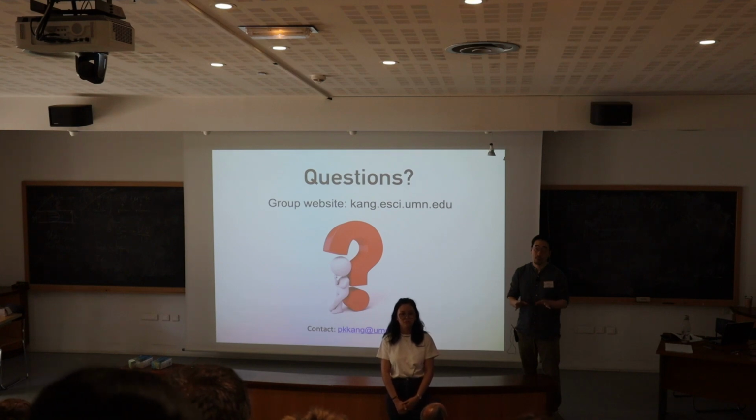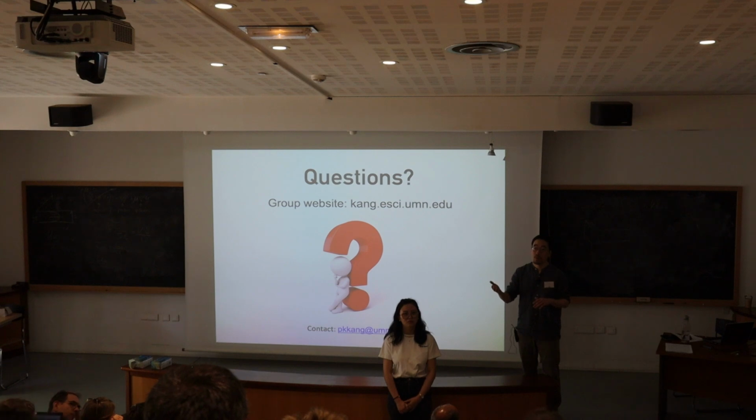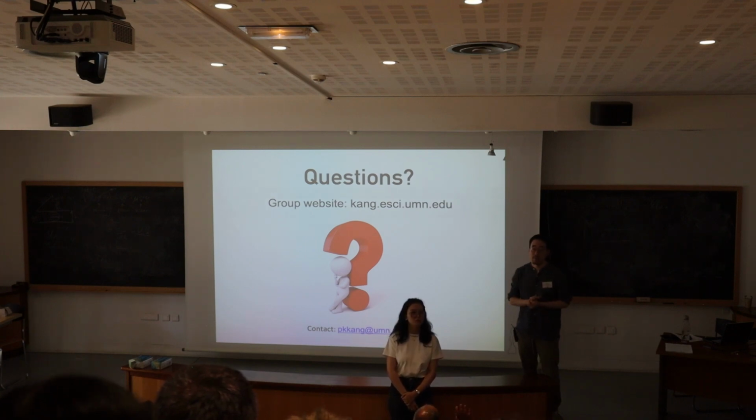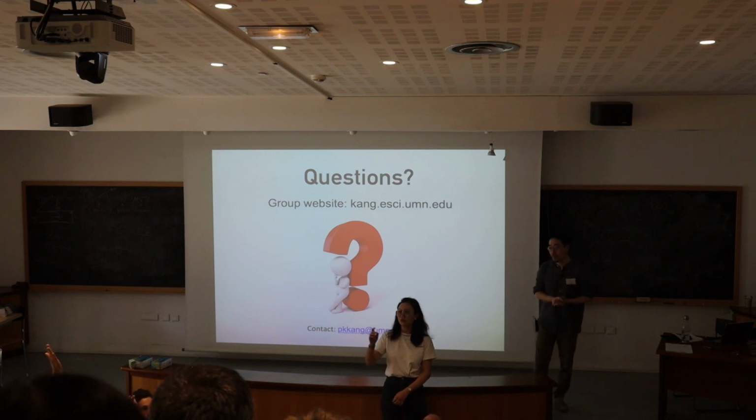Of course it depends again on the specific pore structure, but in general, on the order of Péclet 100, you will start to see it. Already at 100. It depends on the structure, but usually at Reynolds number 1 to 10 you start to see an inertia effect even on flow, and Reynolds 10 is typically, I would say, a Péclet on the order of 1,000. Yeah, thanks.